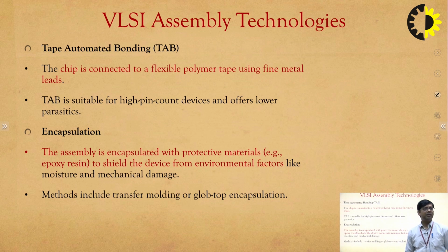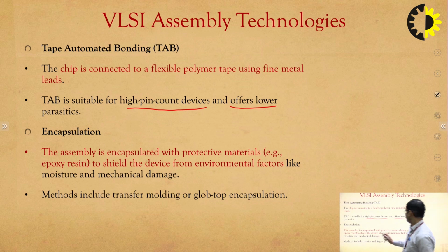Next is TAB, tape automated bonding. Now, the chip is connected to a flexible polymer tape using fine metal leads, and this kind of bonding is suitable for high pin count devices and it offers lower parasitics.